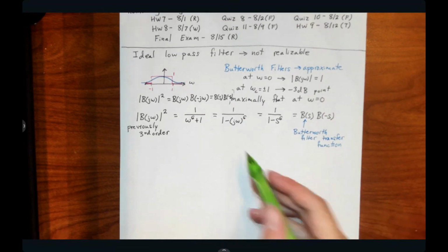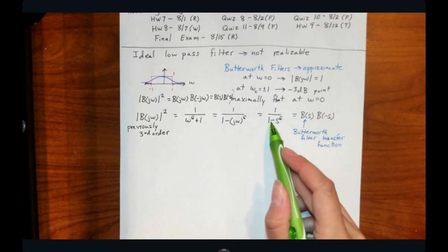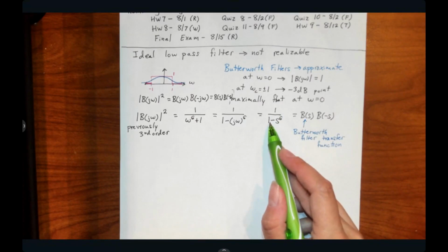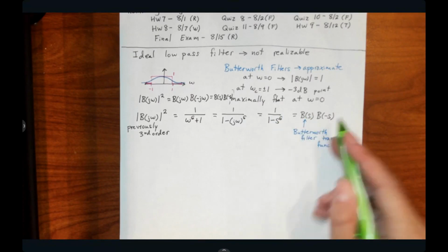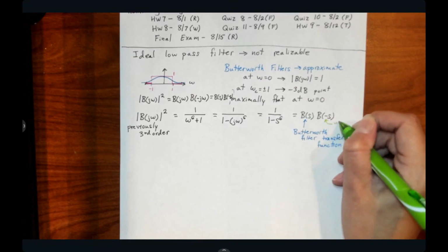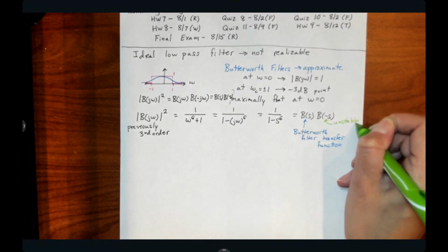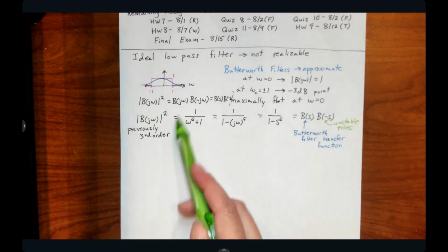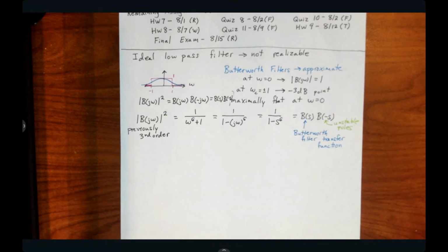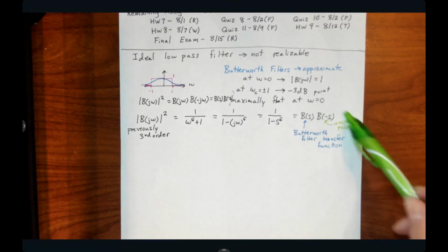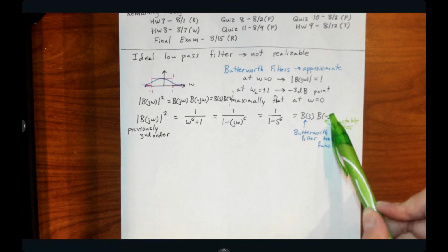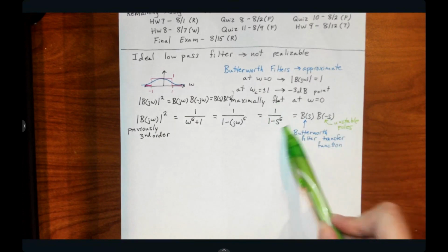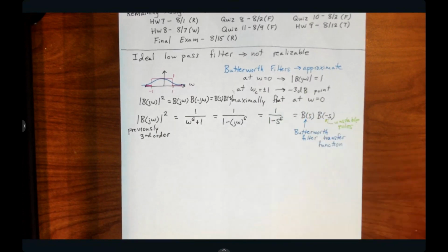What we're going to find is that when we're looking at the poles of this transfer function here, we're going to get 3 poles which are stable and 3 poles which are unstable. Right, and these just came about from using this expression to find the form that we wanted. And so we can throw out all the unstable poles, and we're going to keep the stable poles from here to form this Butterworth filter transfer function.